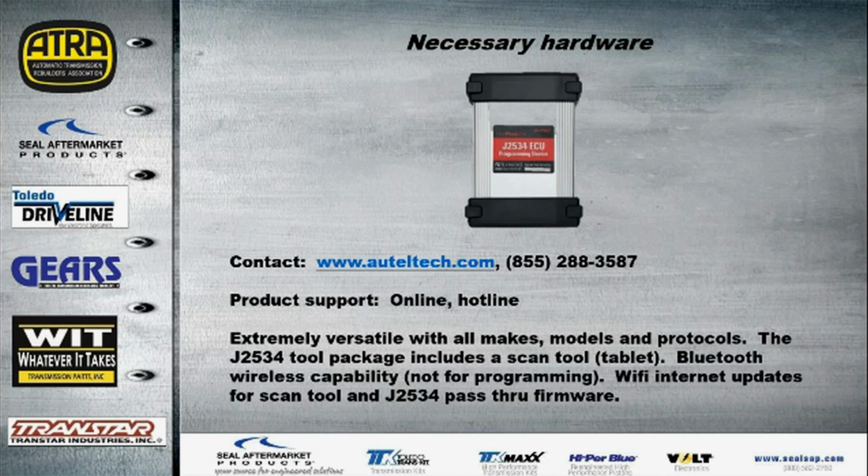It'll walk you through. It also comes with a scan tool. A tablet type scan tool comes with this, and they have a Bluetooth wireless device for the scan tool. Now, the Bluetooth wireless will communicate with the J2534 box as well, but you don't want to program using Bluetooth, okay? Don't do it.